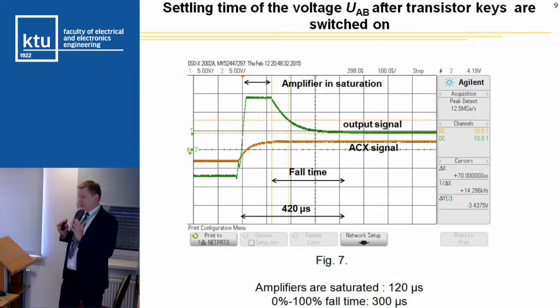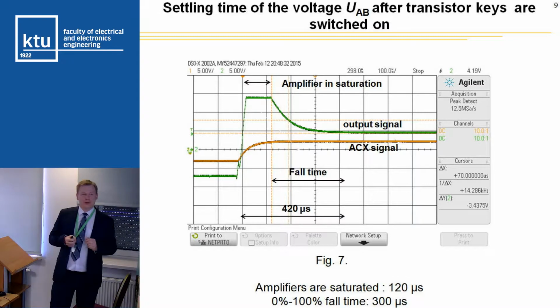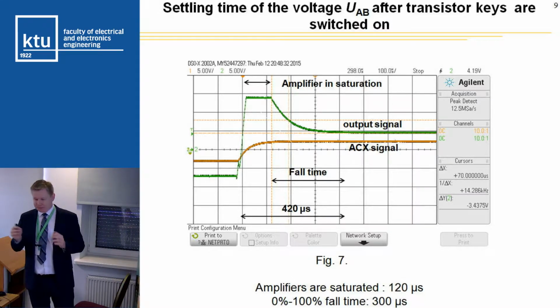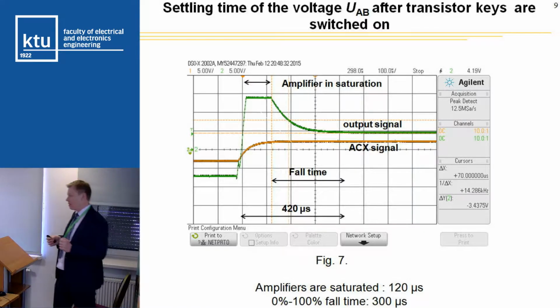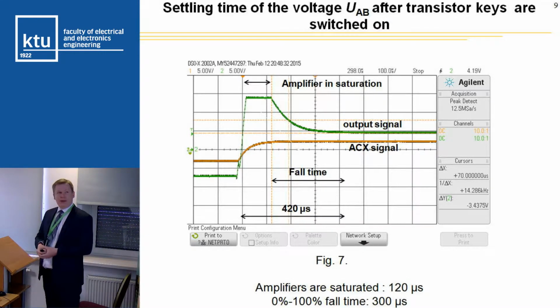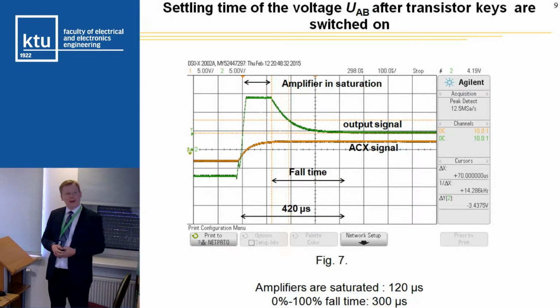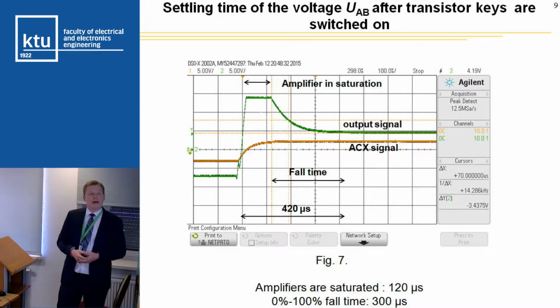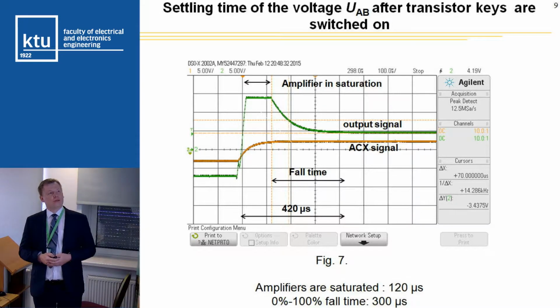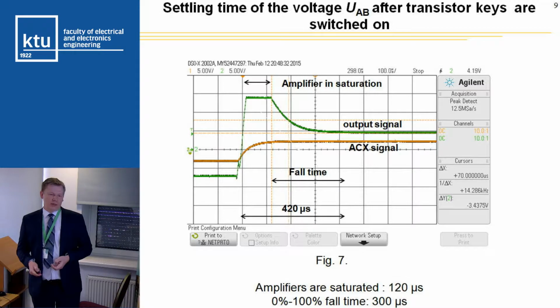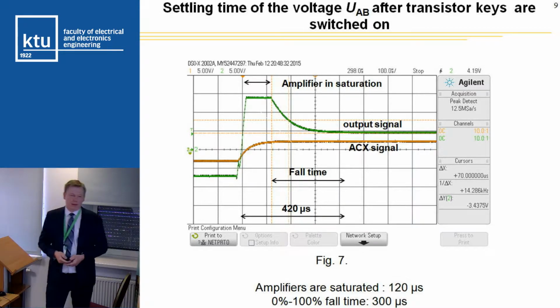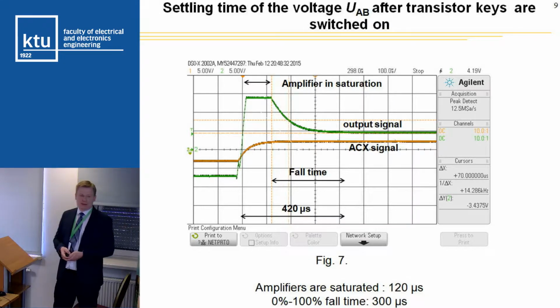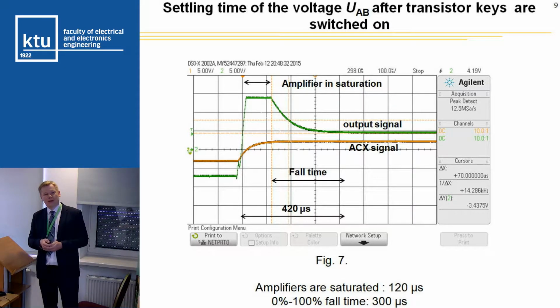But it is not so ideal, because if we have a current source and it is switched, we have unsteady states, and amplifiers get into saturation state, and it takes time, of course. Amplifiers are saturated for 120 microseconds, and fall time is longer, 300 microseconds.